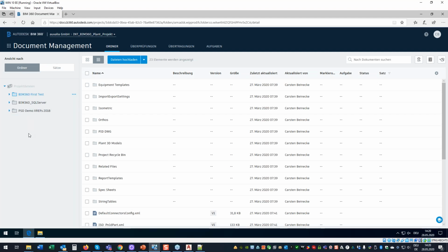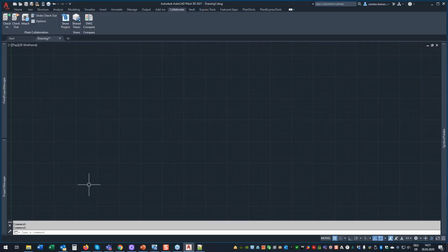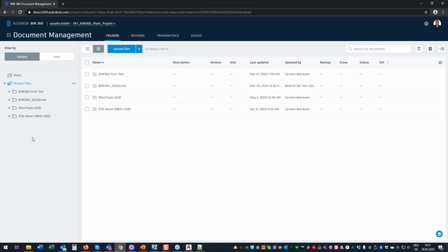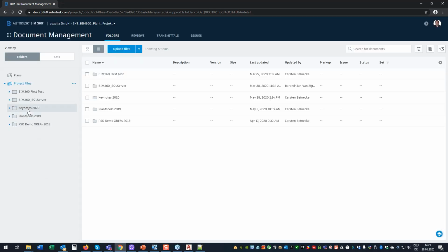So, but you don't see this project here. You would, because this here I'm with a different username. So you don't see that. And this is what is meant by inviting people. So if you want to invite someone to the project who's not in your company, let's say a customer or some vendor or some subcontractor, what you need to do is you give him access. And you do this by, first of all, I need to refresh here as well. So now here in BIM 360 Docs, we also see the project.